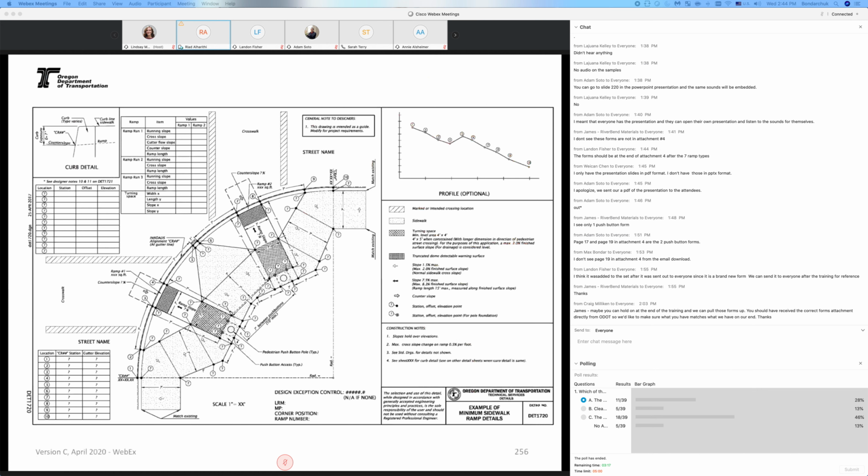I mentioned earlier, try to sketch it. You will find a good design. You will find the profile of the flow line to make sure you don't have ponding. It will give you the ramp, the turning space, and the slope. If you have on one ramp, for each ramp, you may have ramp 1, ramp 2, ramp 3, depending on the type of the ramp.